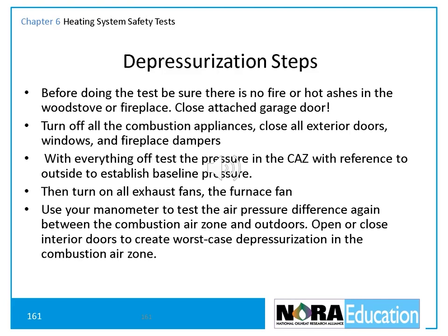There are probably hazardous chemicals, cleaners, degreasers, insect repellents, and poisons in the garage, as well as carbon monoxide from the cars and other internal combustion engines, and possibly gasoline fumes. You do not want to suck any of these fumes from the garage into the house. Be sure to turn off all the combustion appliances. Close all exterior doors, windows, and fireplace dampers.